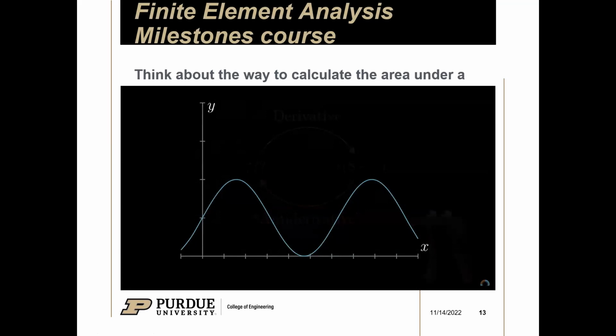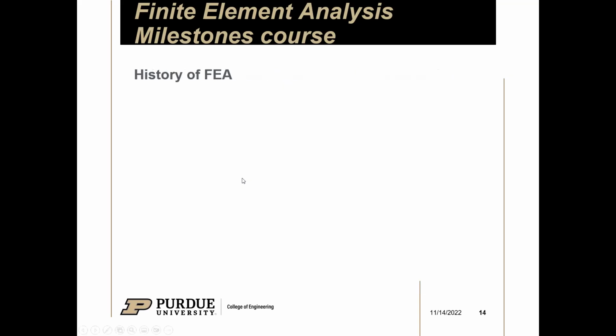You will create a mesh, which is a bunch of tiny little triangles or squares, or however you define the shape, and you'll make these as small as possible to get as accurate a result from your simulation. And with this, there are a lot of factors that you can change that we'll go over later. But if you have, say, a corner, that will need to be more precisely simulated. You can make the mesh in that corner really, really fine, and you can really understand what's going on there.